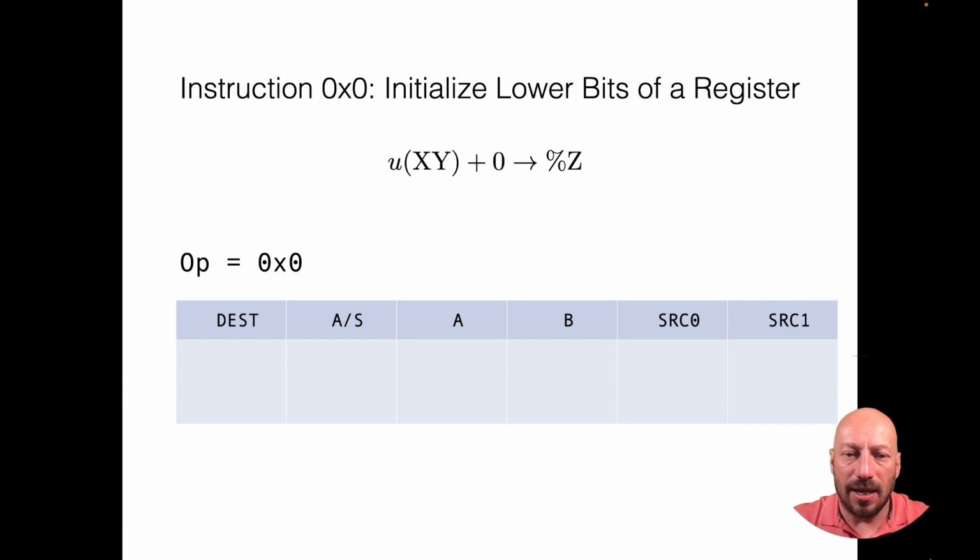That means I have to specify in this first entry what is the destination register, how to identify it, where I identify it with this bit pattern offset. So that's it. What kind of operation is required? Addition or subtraction? Well, addition. What should this operand A for the adder be? Well, this bit pattern of X, Y but 0 extended. And we have a building block for that, so no big deal.